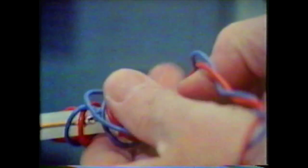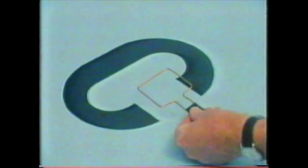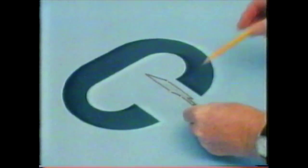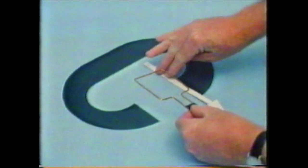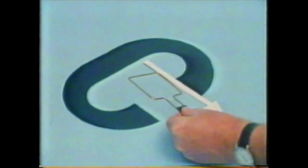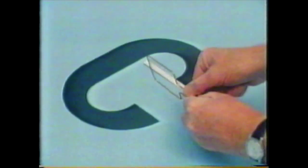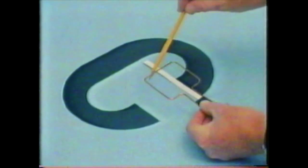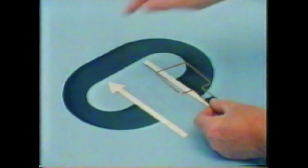But of course the wires get all tangled up. This is what's happening. When the loop's moving through this position, the current flows down the right-hand side in this direction. But the loop continues to rotate, and when that side has come across to here and is moving upwards through the magnetic field, the current induced now flows in this opposite direction.